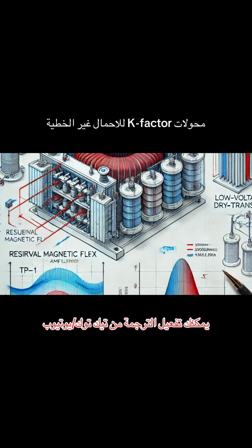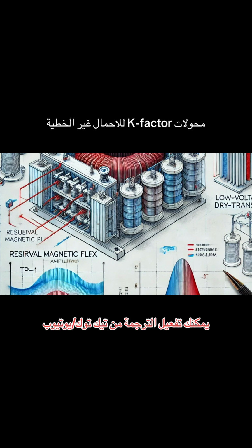Yeah, this is super important to understand. A K-factor transformer is built tough. It's designed to withstand the extra heat from those harmonic currents without getting too hot itself and failing prematurely. It's not about filtering out the harmonics, it's about enduring them. So it's built to take the punishment.